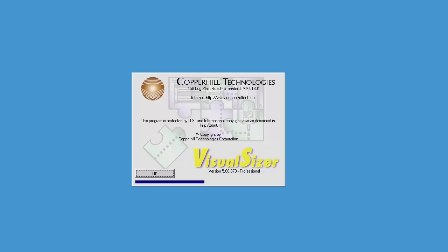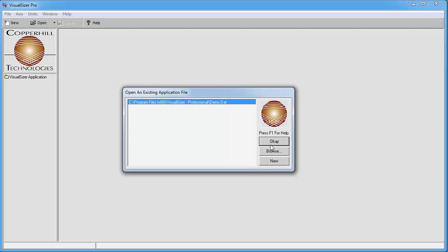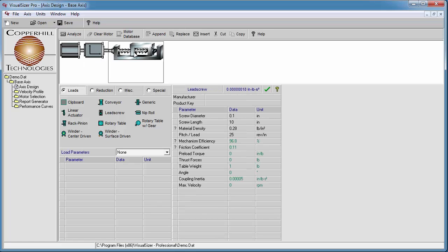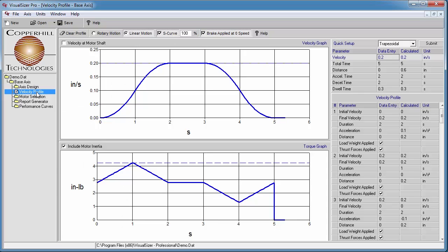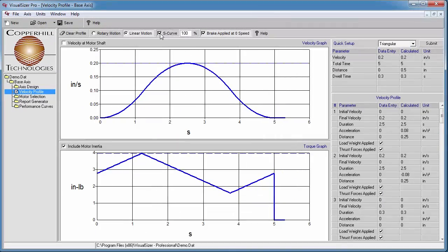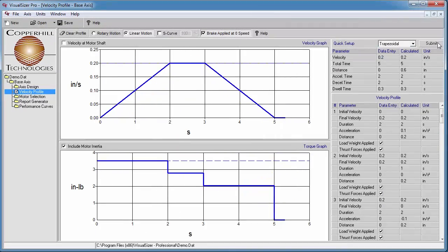Which reminds me, did you know that Automation Direct has a free tool that helps you with all of this? It's intended for servo systems, but it works perfectly for steppers too. You just build your system, enter each device's specs, specify your velocity profile, specify your motor, and you instantly see how much torque you'll need. And it even handles S-curves and triangular and trapezoidal profiles.